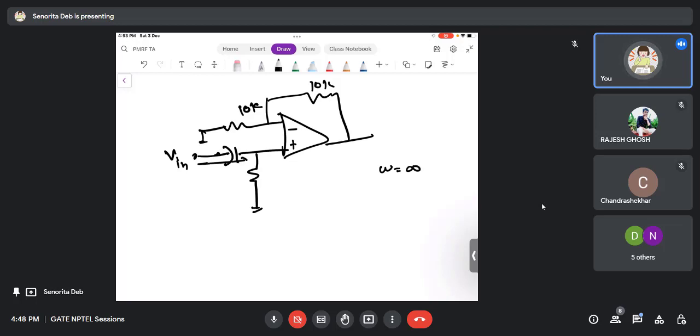The signal is going to get in, right? So what was the DC gain for your low pass filter is the passband gain for your high pass filter. I cannot call it DC because obviously I am getting it at some other frequency. You understand? Yes, ma'am. It is clear, right? Don't get confused with the terminology.